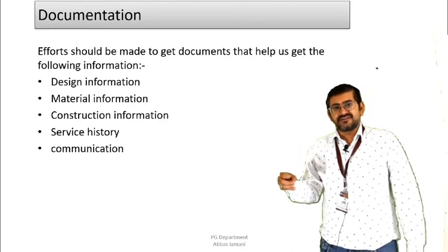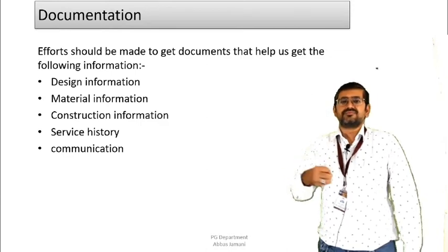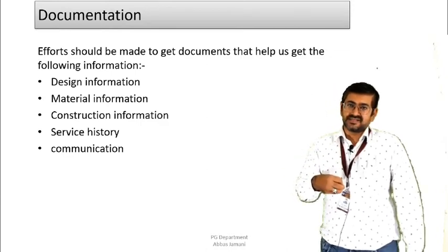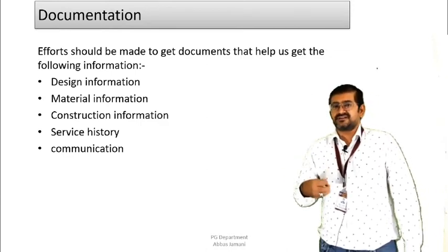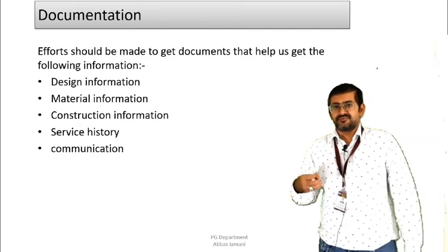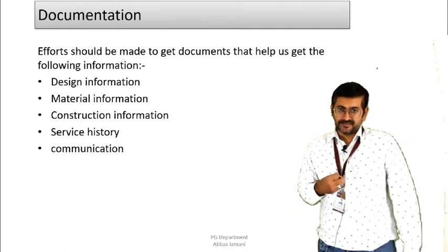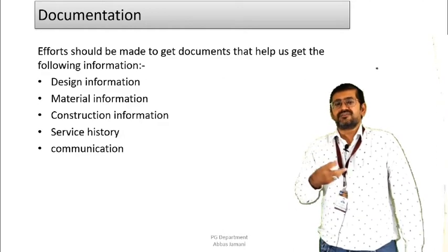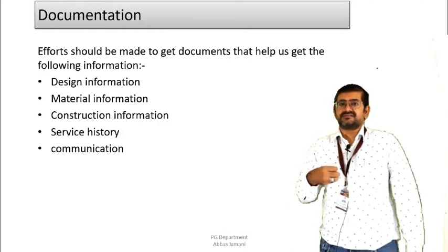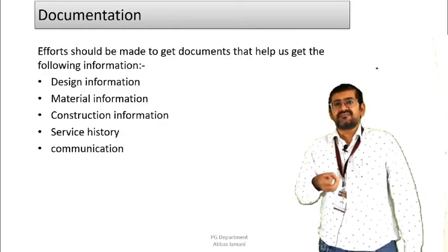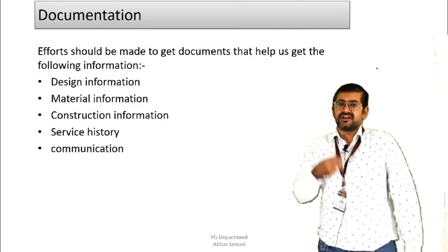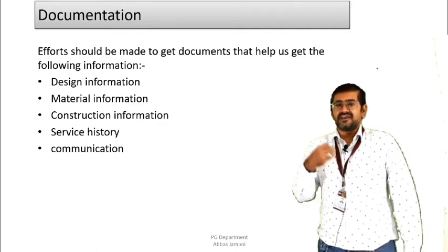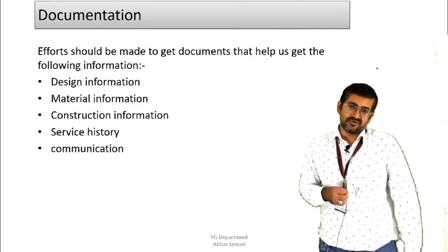Then the results of the test report, results of cube casting that is done on the site for each of the batches, whether it was mentioned or not, and whether it is being reported in the form of document or not, right? Then any verbal communication or any other communication or any reports that are presented by the contractor or any third party investigation agencies, and whether the access to these reports is available or not.